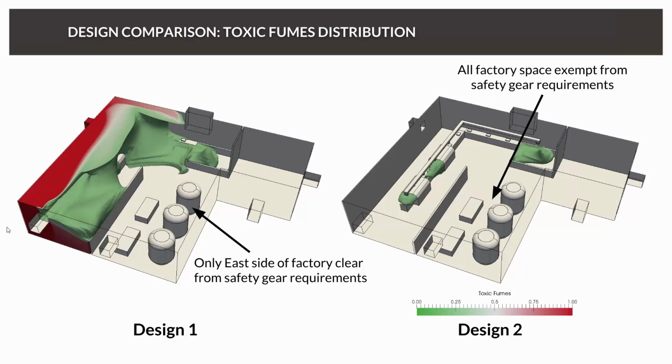In the meantime, just to put it in a nutshell, when creating the contours, what we're actually doing is connecting all cells where the value for the concentration is higher than, in this case, 0.5. And then we are looking for the largest closed surface which we can wrap around the cells. So this is a contour plot, and basically everything inside this region is contaminated.